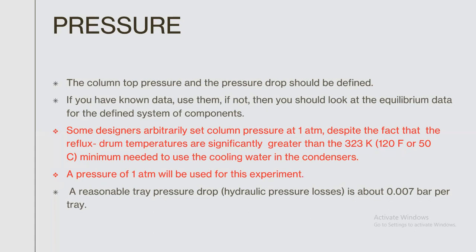A pressure of 1 atmosphere will be used for this simulation. Also, a reasonable tray pressure drop is about 0.007 bar per tray. So we'll go back to our simulation environment and define this.